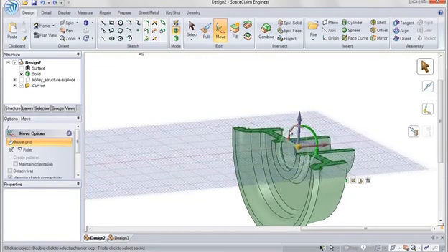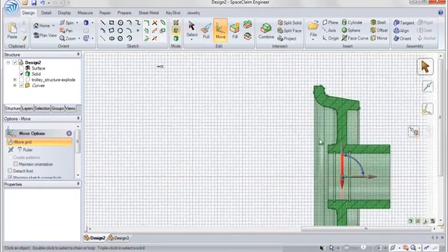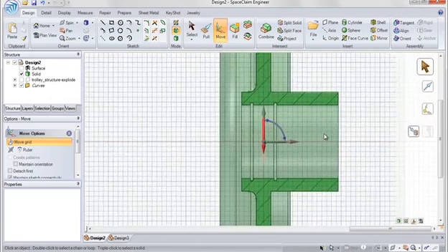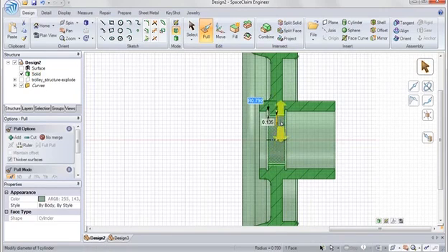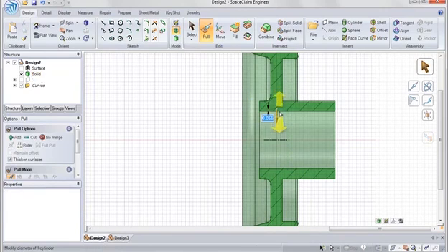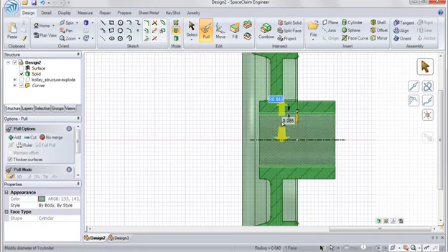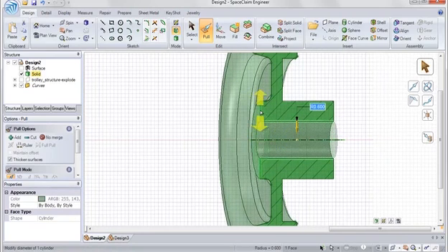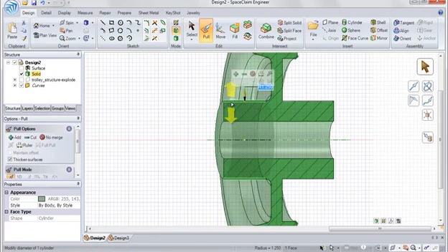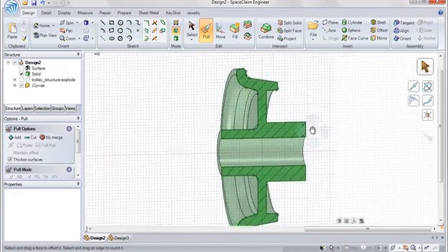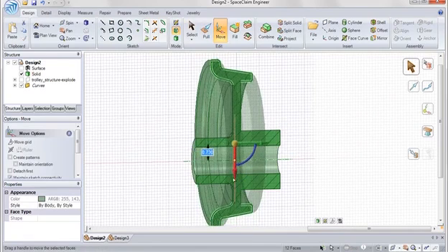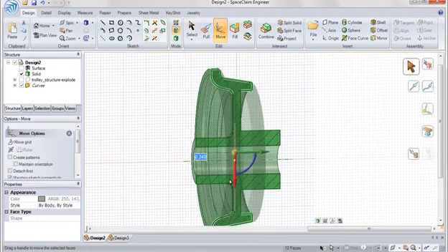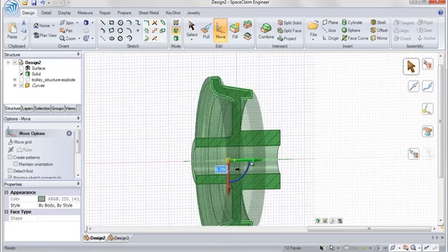Make sure we angle that the right way. And now I can see that in a 2D layout, making these changes again, pulling on any of these, holding down Shift to easily snap to other geometry, changing the inner diameter of that tube, changing any of these layouts, or using the Move command to recenter the center of that pulley, or move those side to side.